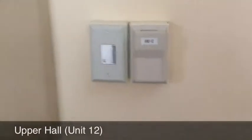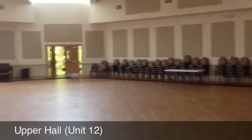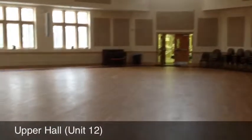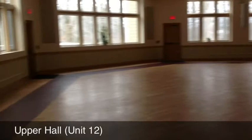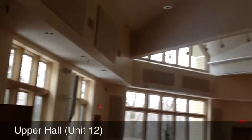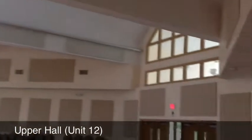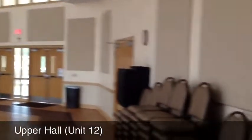We're inside the school building in the main upper hall. We've seen the dry bulb thermostat and the CO2 sensor for air handling unit 12. Air handling unit 12 serves this entire room both with outside air and conditioned air. There's an electric duct heater that serves this space, controlled by the building automation system. We'll show the breaker panel for the duct heater later in this video.